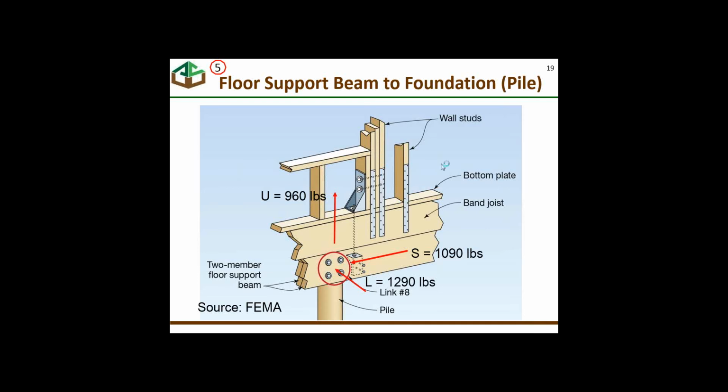Now, that goes to another point, however. Some of these connectors could, in fact, in a pile-supported foundation, be someplace in the middle of the span. And whether the connector is in tension or compression, you do have to design the beams or the floor system to be able to resist additional moments caused by the tension and/or compression in these hold-down connectors.